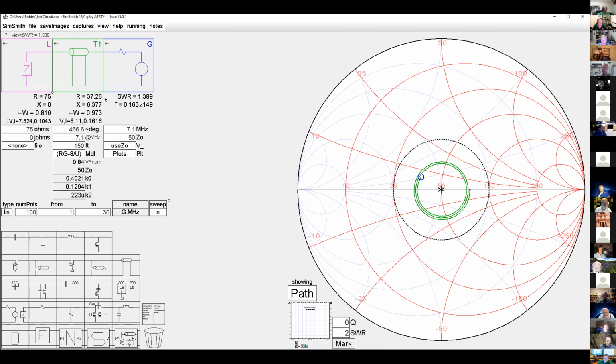Standing wave ratio is still a good tool, but it's not the only tool. So if you take this to its ultimate, the best thing you can buy is the lossiest transmission line you can find, and you'll always have a good standing wave ratio. You won't work anybody, but you'll do well. You'll have good SWR. Robbie, I think the point is that you use the tools to lower the SWR as much as you can. For a given setup, the lower SWR is better. That's really what it comes down to.